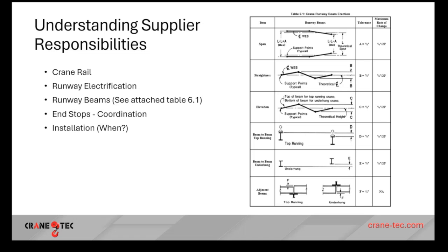They would get missed. And so about 5 years ago, I started putting just a little bit of money in every project. And I always send a set of end stops with a crane. They don't always get used, but I always have end stops so I can put them up there and we can just move on with the project and not worry about who missed them and why they got missed. I cover them on my end, but I always ask also ahead of time. So end stops, again, it's just coordination, talking with your subs, asking the pre-engineered building supplier, and talking with the crane supplier.